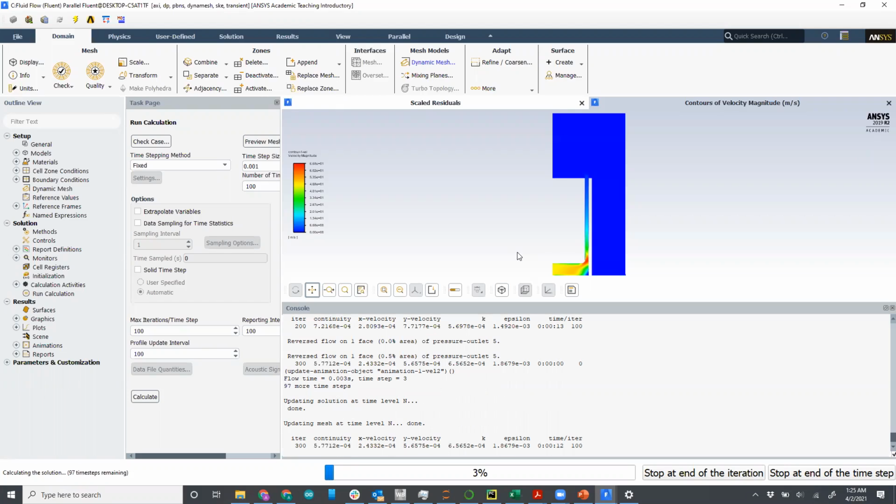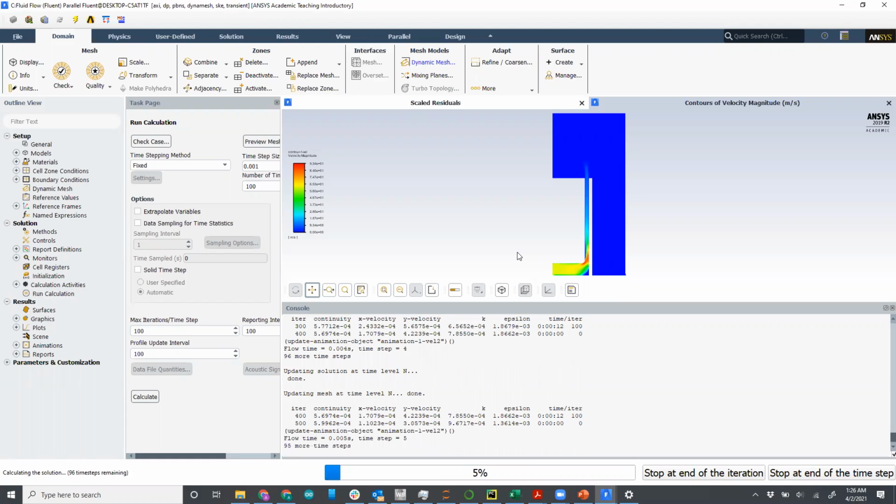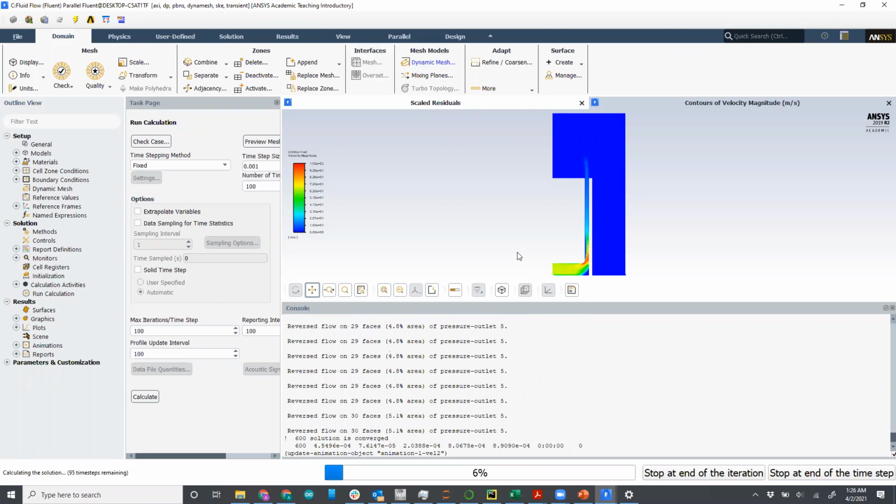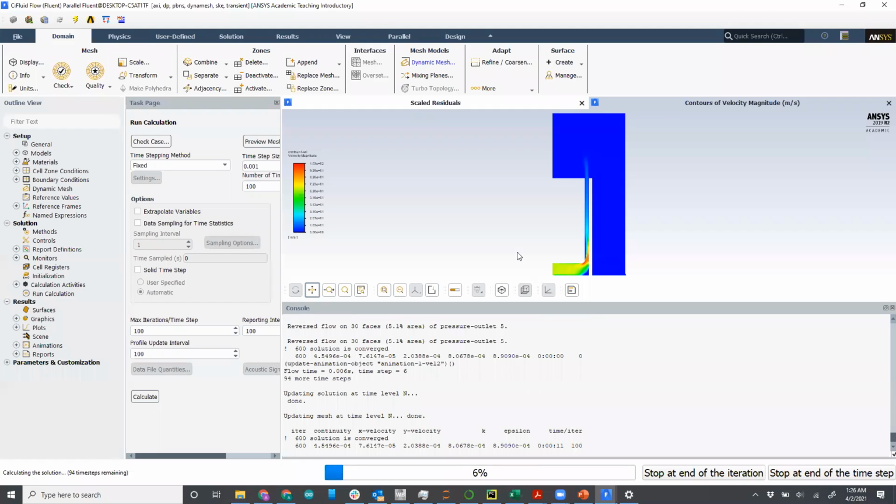So a few things to note here. The interesting knobs to turn on the simulation, or at least what we found was interesting. You can change the inlet pressure boundary condition, and then you can also change the backstop and the front stop, which are in the dynamic mesh settings. Some combinations of those work well, and you can get some interesting oscillating behavior. Some combinations of those result in that negative cell volume thing if the simulation doesn't have enough time to update its mesh as it runs.